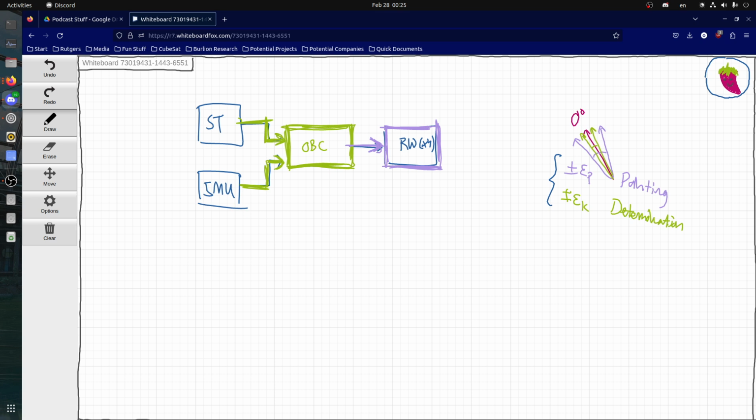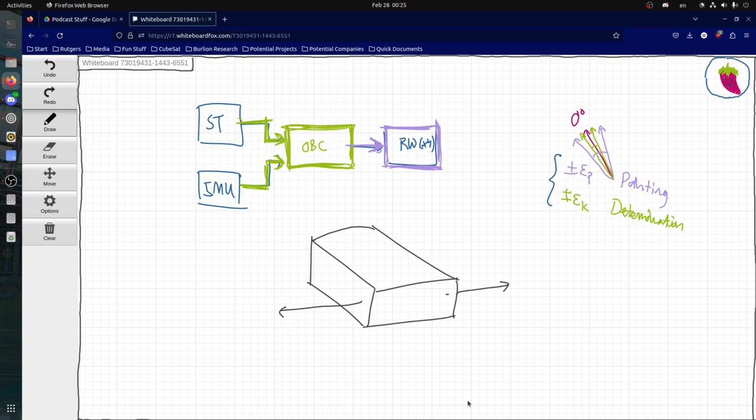The UNP said I don't have to care as much, but I do think I'm gonna think about it. Regarding the Earth case, the simplest solution would be to have two star trackers pointing out opposite ways, so at least one of them is looking at the night sky. Right, but then the payload's on the other side. Yeah, that's tricky. So for us, we would have to have one star tracker pointing out this way, one of them pointing out this way, and that would be very annoying.